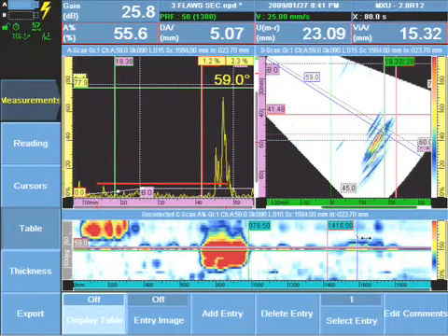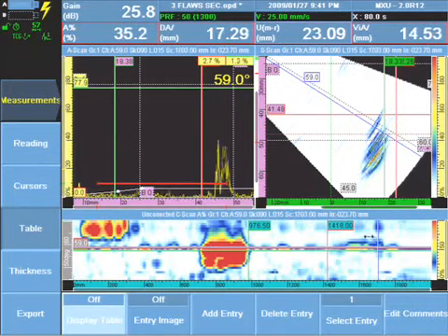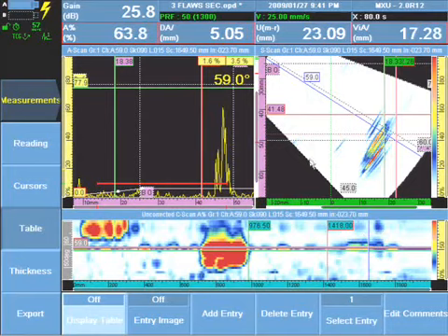Notice the multiple jagged peaks and edges, long rise and fall time, multiple tip diffracted signals. We know this is connected to the surface because it plots right at T1. We have a very clear, sharp, multiple peaks indicative of an outside diameter crack or toe crack.